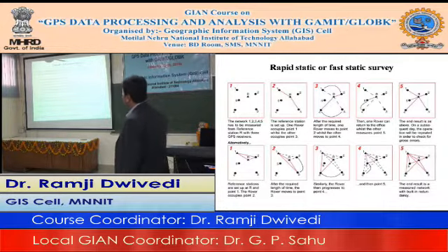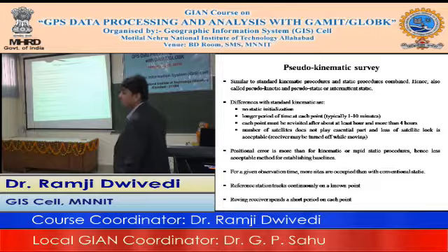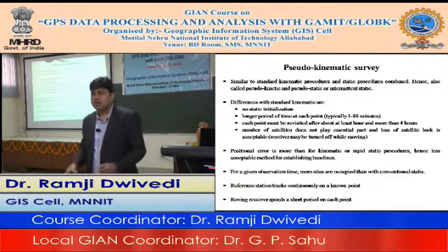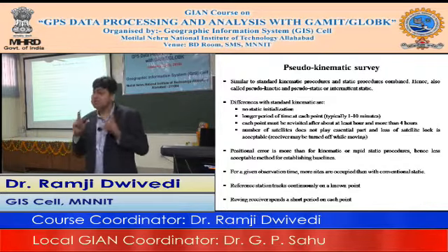There is another one, the pseudo kinematic survey, similar to standard kinematic, where you have a base and a rover, and after initialization the ambiguity is resolved, you can move, so the lock is maintained in this case.